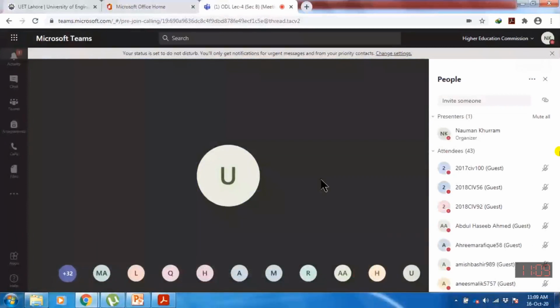It means that I am considering the stress concentration in the plate, which is in contact with the bolt, which is the circumferential portion of the plate which is in contact. When we consider the bolt, we will consider the bolt stress in our design case. So a small portion of the plate at the section at the connection is transferring the load as compared with the section where we haven't considered load. You got the idea now?